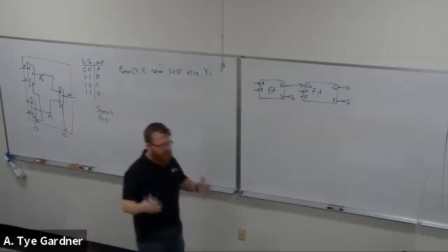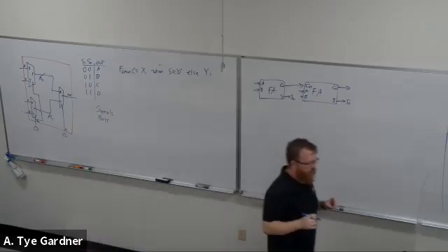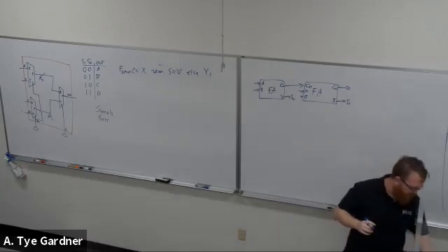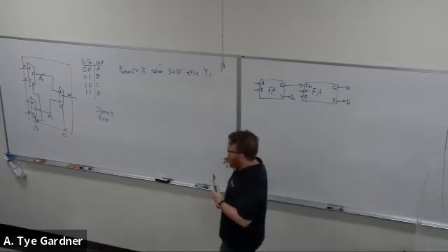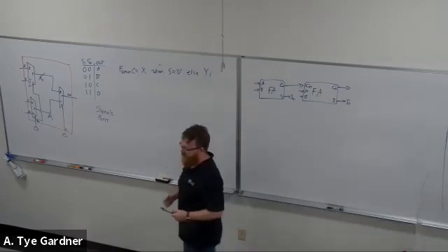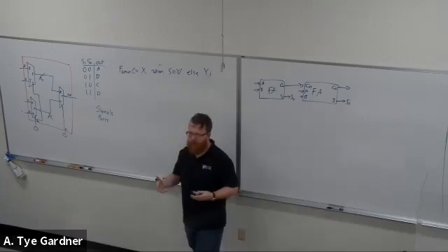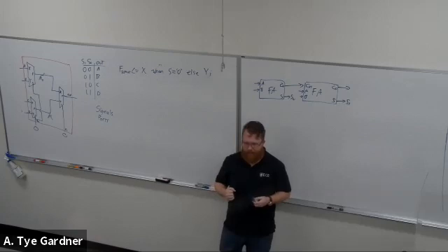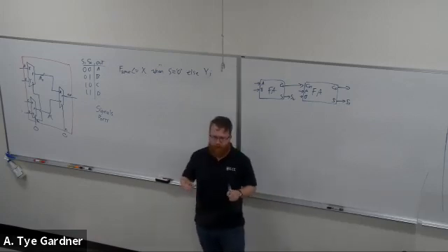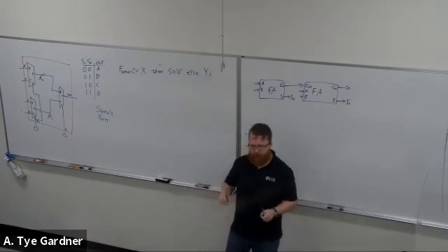Now, in our code, VHDL doesn't know that anything exists, okay? So how do we tell it exists, right? Where do we start? Well, there's this idea of an entity, okay? And you're going to hear me use two words, and I'll come back around, I'll use them all the time. One is entity declaration, and then you'll also hear instantiation, okay?